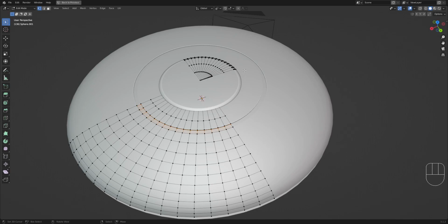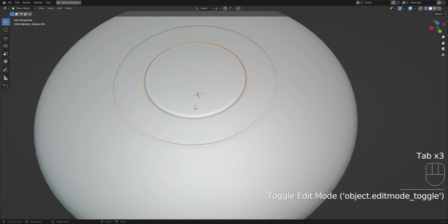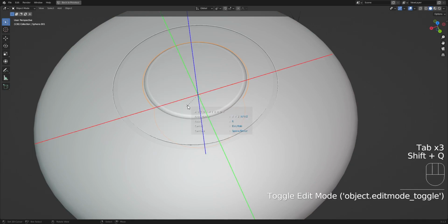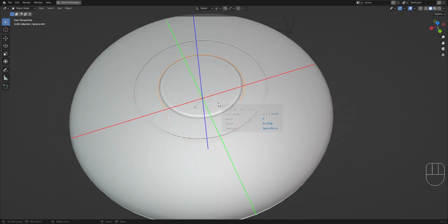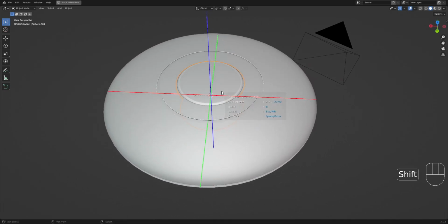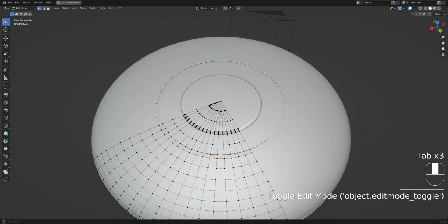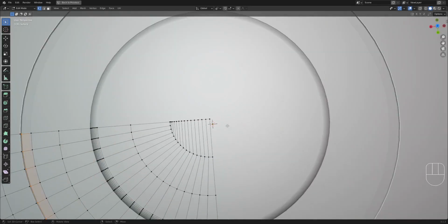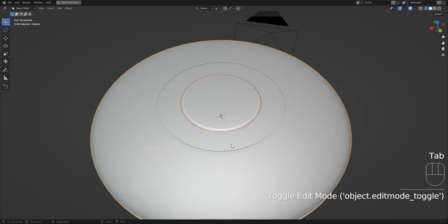Actually, I'm going to transfer the geometry of this top part here, on a mirror. Pick this side, and this is already using the mirror modifier, and the XYZ axis is already turned on. So I'm going to press space to confirm the operation, and we have the real geometry of the top hatch on this side.